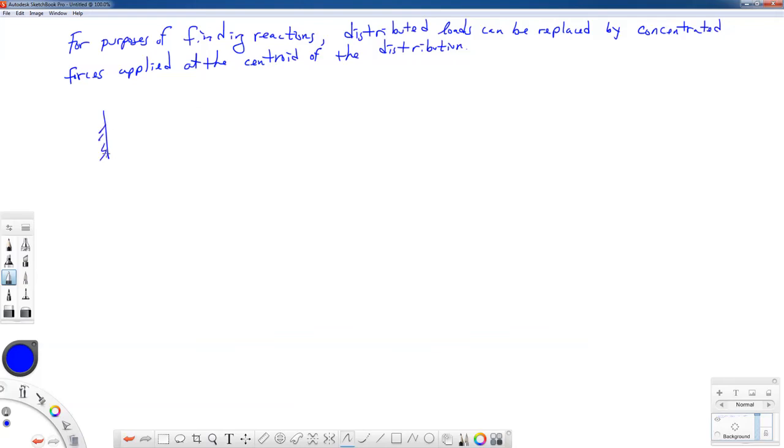Suppose we have our cantilevered beam of length L, and we have a triangular distributed load on it. And the height of the distribution over at the wall is, let's say, W0. Well, I can do my free body diagram and I can find my reactions at the wall. I can list them down. I know because it's a cantilevered beam, I can have a moment at the wall, I can have a force in the horizontal direction, I have a force in the vertical direction. Let's say if this is point A, we'd have AX, AY, and MA. And then I have my load that's on this beam.